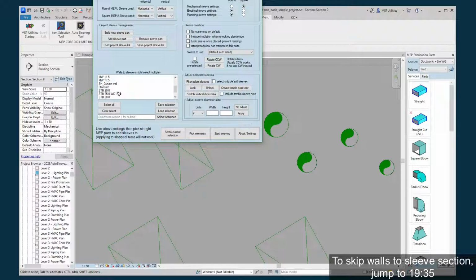You can also, let's say I want standard, but I also want all the STBs. You can also use the search tool here, and it will select all the things with STB. So if there was something up here with STB, or in this case I guess stud is up there, so I could just do stud, and now those items are selected as well. You can just add and remove them as you need.